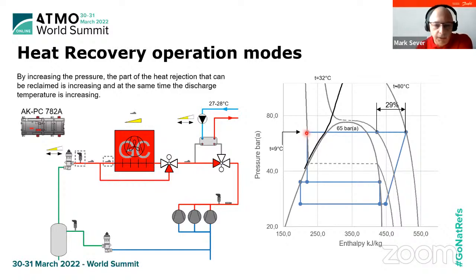But of course, if ambient temperature is very low, then fans will tune not to have this value move more to the left, because then you will have problems in your CO2 system because you will not be able to control pressure in the receiver.